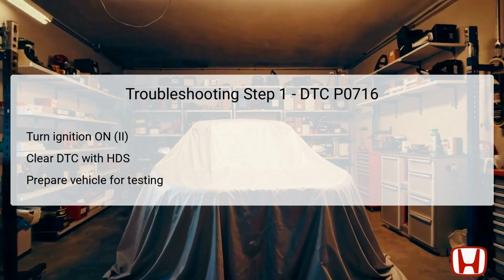Following this, the vehicle must be prepared for testing by either securely supporting it and allowing the front wheels to rotate freely, or placing it on a vehicle lift. This preparation is necessary for conducting a test drive while monitoring the vehicle's performance under specific conditions that can help replicate the issues indicated by the DTC.